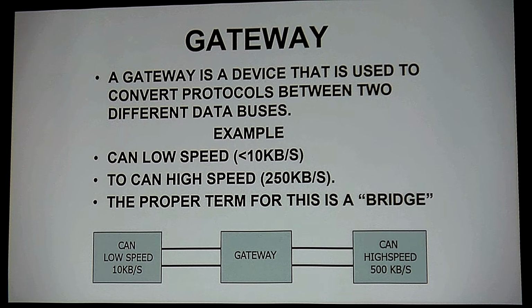We're banging out 200 messages on Class C at the maximum rate, but we're banging out 10 on another bus. Well, that's like having a Volkswagen Bug going around a Formula One track. It ain't going to work. You're going to have wrecks and collisions. I have to isolate these two systems. I'm going to isolate them with a bridge. A bridge is a way that I can transmit data from one side of the system to the other side of the system.